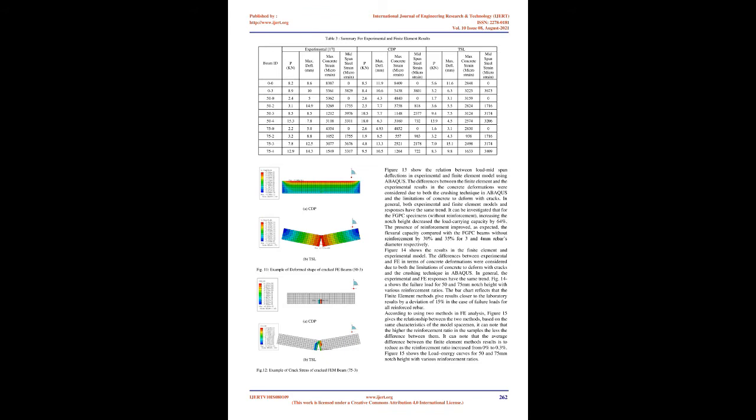Material properties. Concrete elements. There are multiple parts of the material model for the concrete element. It is used for all the concrete elements, and it is meant as linear isotropic for the elastic zone of the concrete, and multilinear isotropic for the plastic zone of the concrete. The elastic parameters required to establish the tension stress strain curves are concrete elastic modulus, EC, and concrete tensile strength, FCT, according to the experimental results.